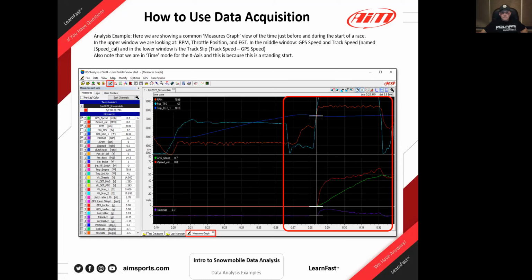There's a lot of other detail here. We can look at it in time or distance. We can put track maps up. We can put the GPS map up. We'll look at some of those options here in just a moment. But that's the basic layout. And if I wanted to add another channel, if I wanted to come over here and add in the temperature of the engine, we could just click on that and tell it which window we want it to sit in and look at the data. And this is data from a Polaris. The Ski-Doo and the Arctic Cat have the same channels. They might be called something different, but it's all the same.